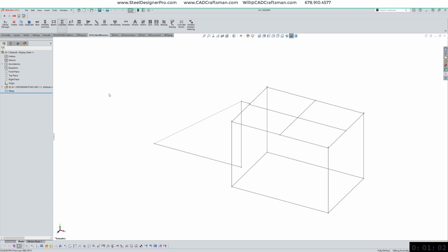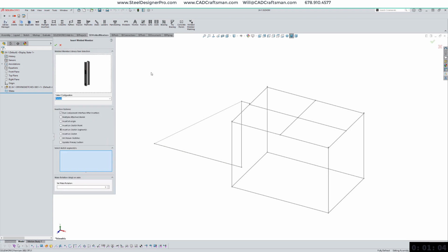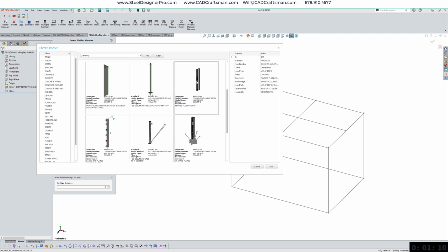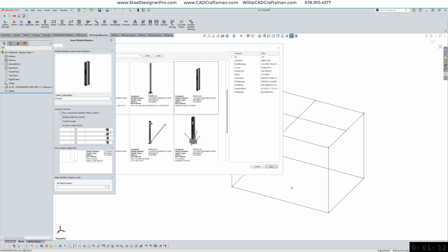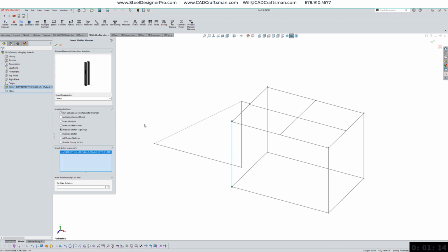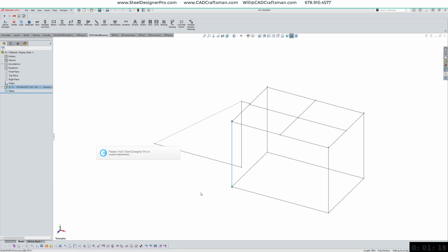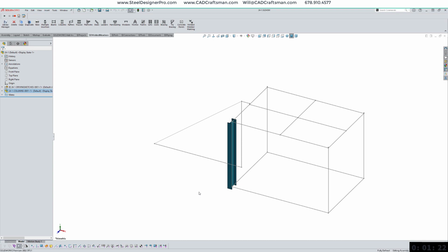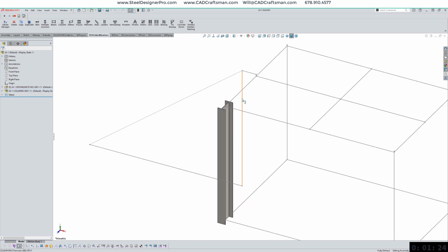By selecting the SD Welded Members tab, the selection filters for beams, columns, and other members become visible. Select the Columns button, and then by clicking on the image, you are directed to the library. It is important to note here that the buttons are simply shortcuts to a particular area of the library. Within the library chooser, you may then select any filter.